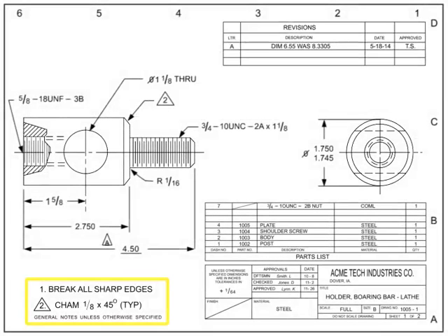The notes list conveys information that the callouts within the field of the drawing do not. It may include general notes, flag notes, or a mixture of both. Traditional locations for the notes list are anywhere along the edges of the field of the drawing, but most are typically found in the upper left or bottom left corners. General notes apply to the entire drawing. Tolerances, general handling or material specs, color specifications, testing requirements, or packaging instructions are examples of general notes.